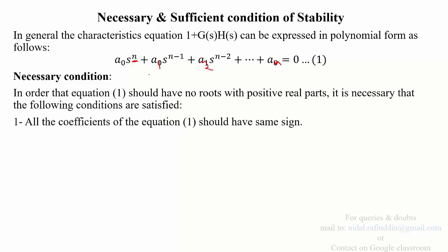So there are two conditions. The first is all the coefficients of equation 1 should have the same sign. What does it mean? If you look at this particular equation, the coefficients associated with this equation should have the same sign.